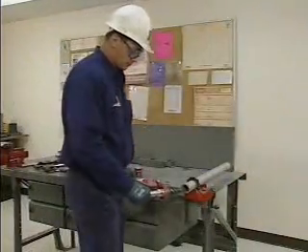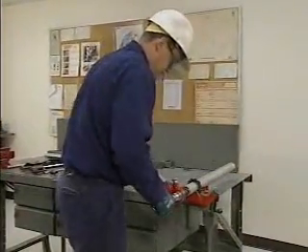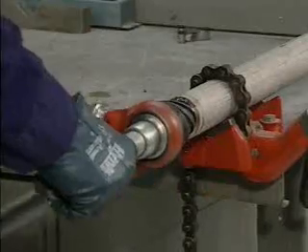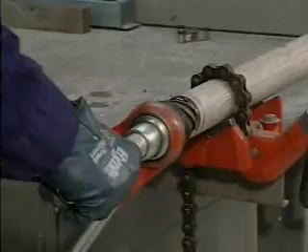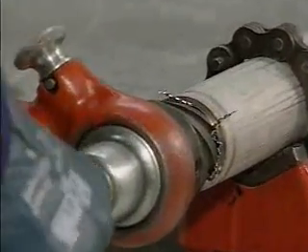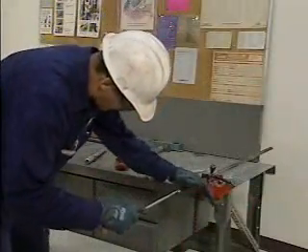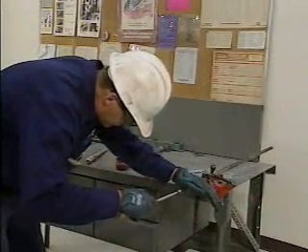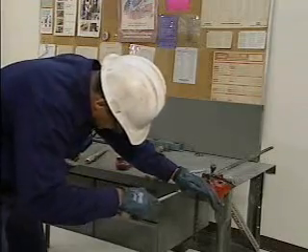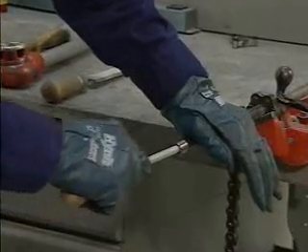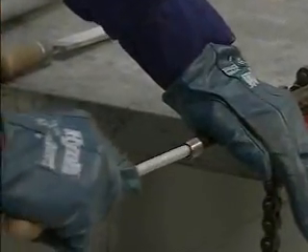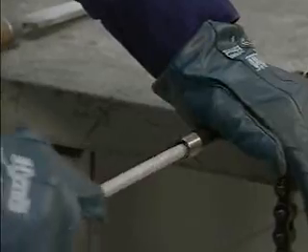Insert the reamer or file into the pipe enough to exert a slight pressure without damaging the pipe wall, and rotate the reamer or file inside the pipe until the pipe surface is smooth and free from burrs and ridges. A rat tail file should be used as a last resort when a reamer or a half-round file will not fit inside the pipe. Rat tail files can leave marks on the inside wall of the pipe, which makes the pipe wall thin and susceptible to early failure.